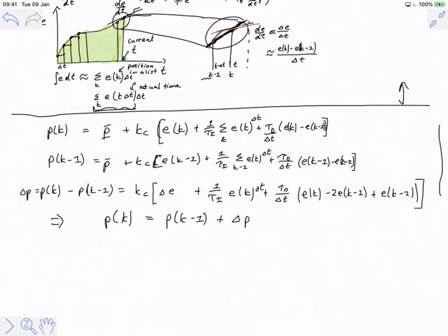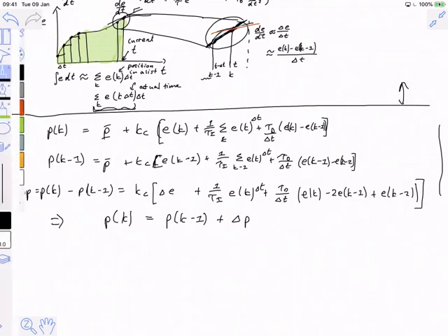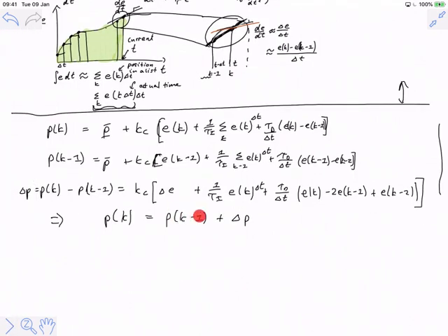If that is the full extent of my program, my controllers will behave identically, whether or not the output is saturated. What I mean by that is, if I remember the pk minus 1 that my program calculated, and I use that to calculate a new pk, it doesn't matter whether the output saturates or not.